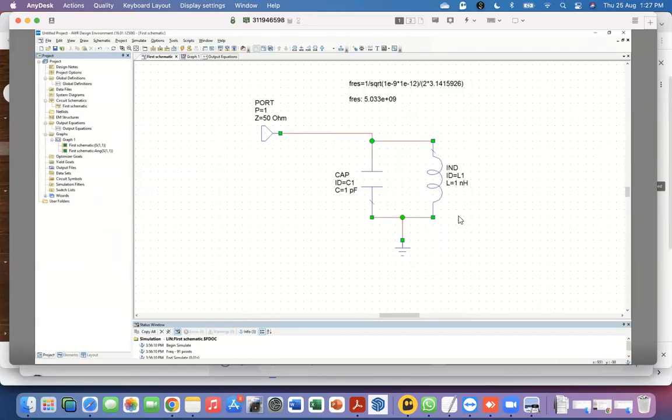It cannot absorb any energy. There's a caveat, which I'll come to in just a minute. Hence, the entire signal is reflected, at all frequencies, because both capacitors and inductors just have different reactances, but they're still imaginary reactances.